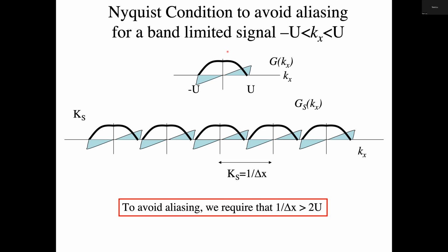It's an interesting aside. What is the band limit of the noise? And how do you get rid of that noise that's at higher frequencies? You just filter it out. You don't want that noise. Just filter it out of your signal. Okay. So if you have a signal and all of your information is in some band and you don't care about the high frequencies, it is often wise to filter the signal so that those high frequencies are known to be gone, right? So we'll just filter at some width and then we're good. That's often done in MR.